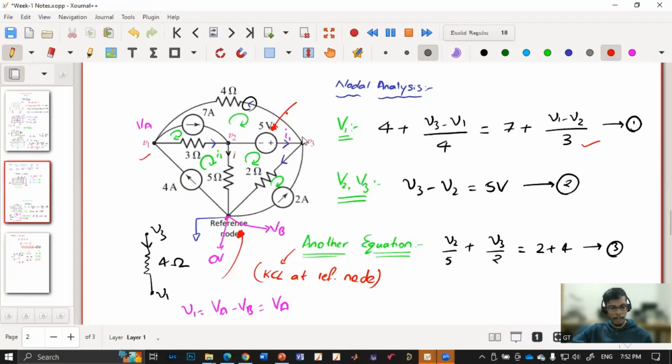Yes. Now you have these voltages. Now you can find the currents in individual branches also. So now you know currents in all the branches and voltages in all the branches. Now you can apply KVL in any loop, or you can apply KCL at any node, and it should satisfy, and it will satisfy if your calculations are correct.